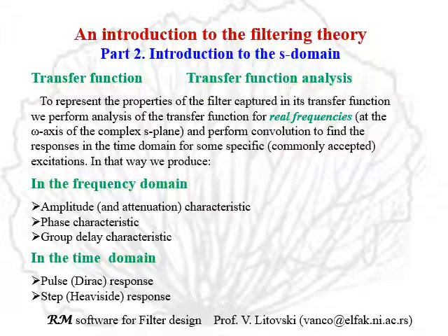In that way, we produce amplitude and attenuation characteristic, phase characteristic, and group delay characteristic in the frequency domain, and then in the time domain, pulse response, which is frequently referred to as Dirac response, and step response, which is sometimes named Heaviside response.